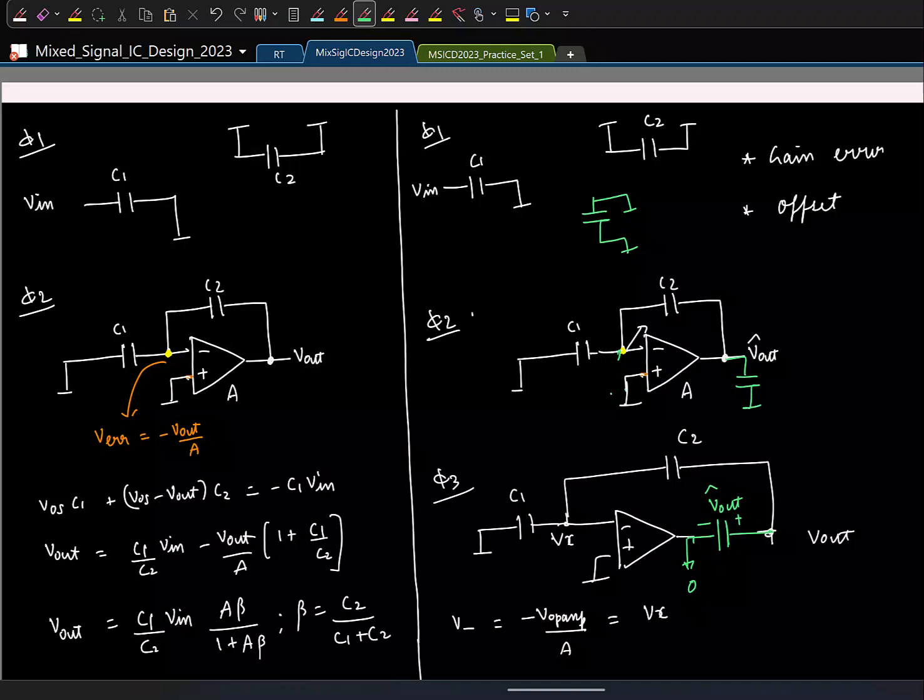So what current flows into and outside the output terminal. Correct. So Vout cap also changes. That is true. So Vout had changed, so that's why you have to size the capacitor appropriately. If, let's say, the capacitor is sized appropriately large enough, then even if some current is drawn, it might not lose its charge.